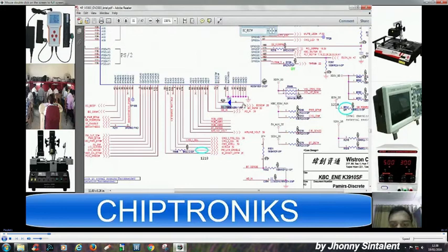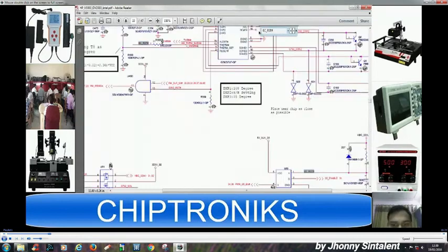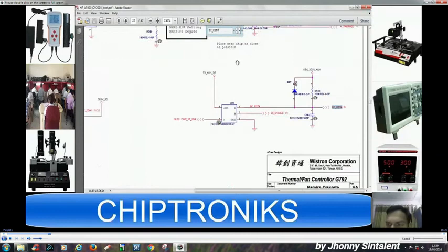You can see this EC reset is going to the input pin of the IO controller also. And from where is this EC reset coming? This EC reset is basically coming from this 3D3. It has been taken from the 3.3 always on voltage and it will be given to the IO controller.